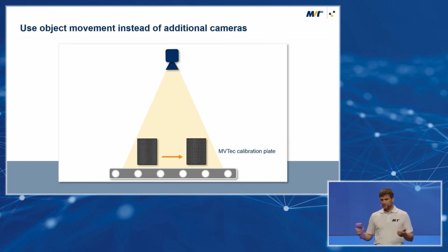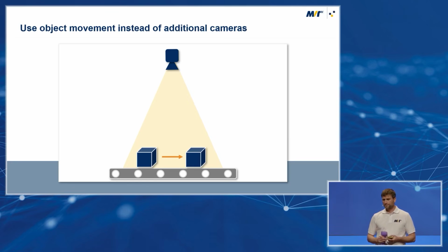We take 2 snapshots, like 2 perspectives, and we also generate a stereo vision. So we have 2 perspectives on the object. Both positions have to be in the field of view of the camera. So this would also work on a conveyor belt with 1 camera. Here, our quadr is going from left to right, and we can detect it.